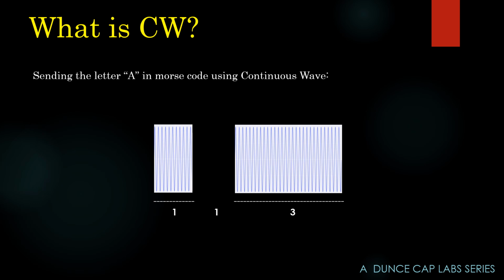Spark generated unstable clumps, if you will, of RF waves. The oscillators, using crystals and tubes or crystals and transistors, generate a continuous wave as long as you keep the transmitter keyed. So in that regard, this is an interrupted continuous wave, so ham operators call it CW for continuous wave.